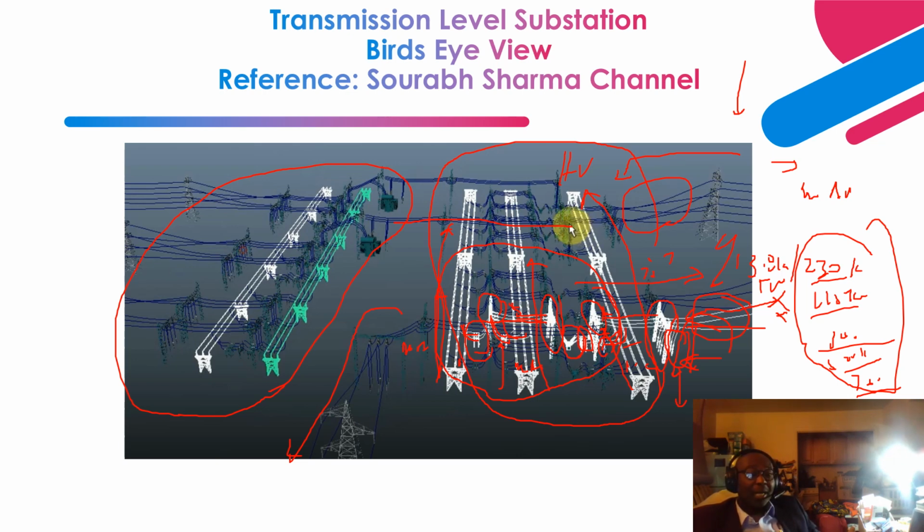Then for this sub-transmission level voltage, similarly, I have a main and transfer bus, an auxiliary bus, a spare. Redundancy has been built into it. Then I go through a step-down transformer from 115 kV to 34.5 kV, or 115 kV to 12 kV. Once I achieve that level of voltage, then I can go out to a distribution level substation somewhere else.